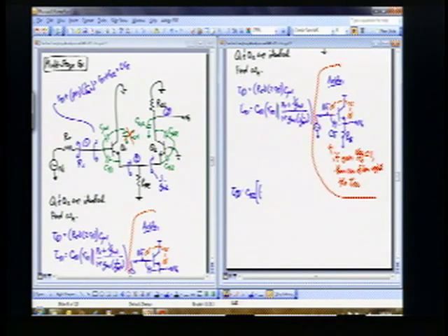GM2? Yes, 1 over GM2 is definitely there. Parallel. I was going to write a different one first, but yeah, write 1 over GM2 parallel RE. And 1 over GM1, which I could neglect, but I won't here. Yeah, parallel 1 over GM1.